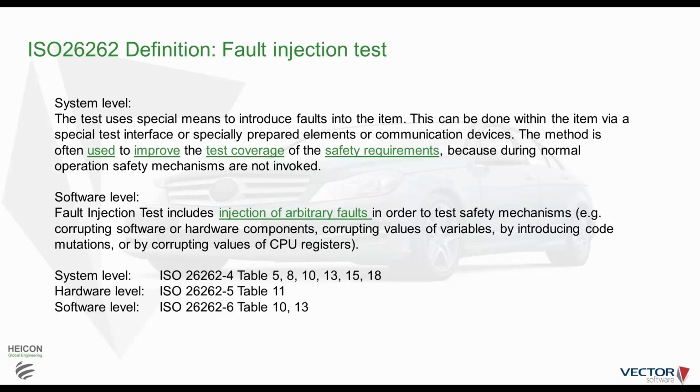There are in the 26262 in part 4, 5 and 6, so system, hardware and software, several places where fault injection is mentioned. You can see in the tables in system level, in 6 tables it's mentioned fault injection testing. Even on hardware level we have fault injection, on software level also 2 times. Fault injection is somehow a topic from system point of view. As you can see, the main focus is on system. I think there is no doubt. However, even on unit testing, you can do fault injection. It's a question of how you interpret, how you define it.